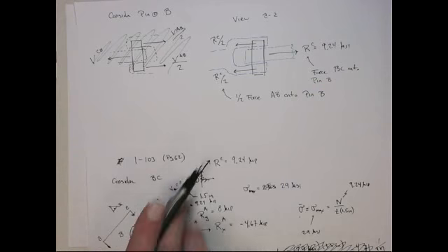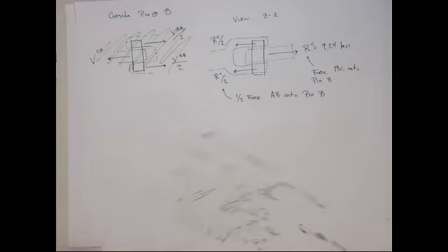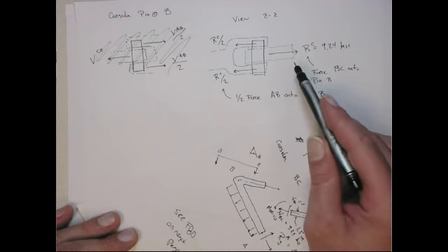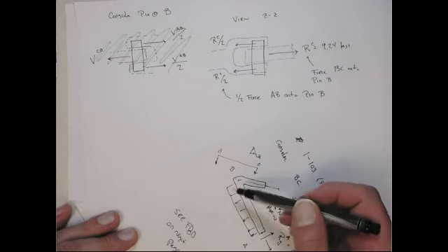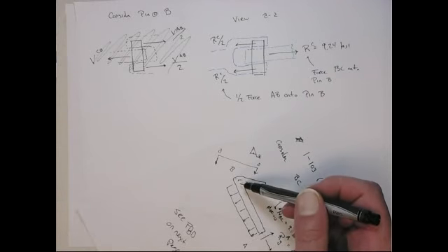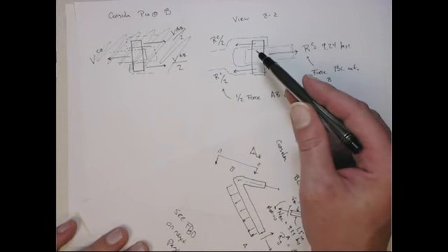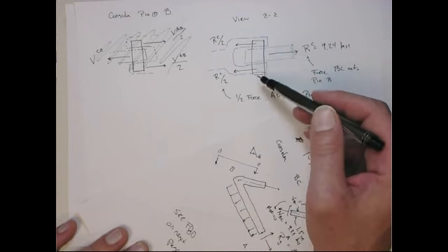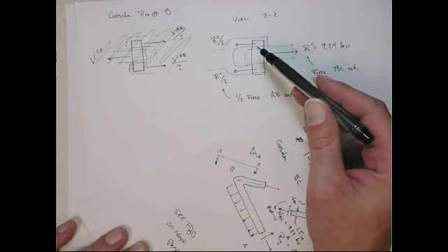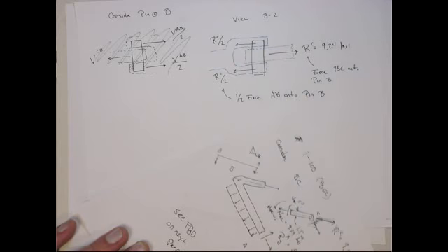Okay, so again, we're kind of looking down this view. So if you look down this view, you have, maybe I rotate this a little better. Right? We know that element BC is a tension, and its magnitude is 9.27, so it's pulling this way. That means that element AB has to act in the equal and opposite direction, but since it's a knuckle joint here, it actually splits that force in half, a half at the bottom and a half at the top. Okay? Total force in this direction sums to 0, right? This is the line BC.